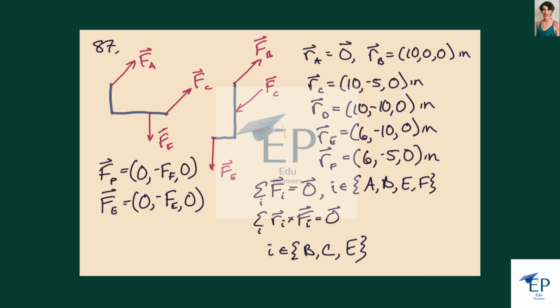So again, we're asked to look at the two different cases, and I'll just look at both of them at the same time. So it's going to be either a load of 100, a minus 100 pounds in the downward direction, either at point E or at point F. And so we can go through the process again, right? Position vectors to our points. I used A as the origin, so we have positions to B, to C, to D, to E, and then to F.